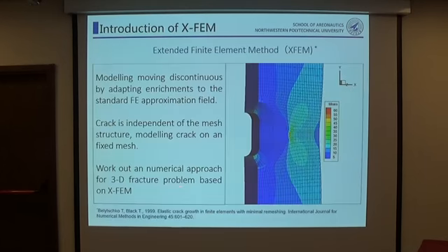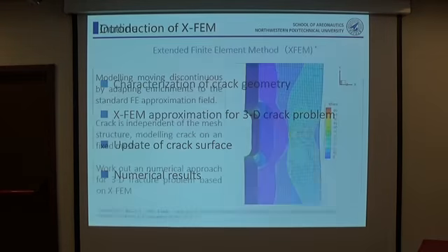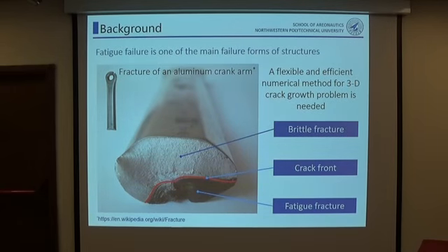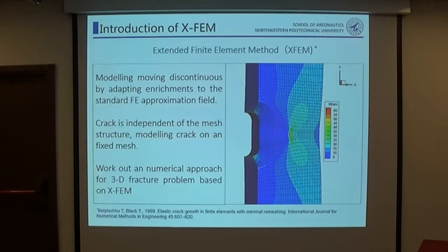The dark part is the fatigue fracture, and we can see the crack surface is non-planar and the crack front is irregular. It is difficult to work out an analytical result for such problems. So, a flexible and efficient numerical method for three-dimensional crack problems is needed.